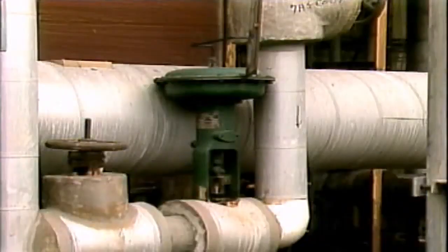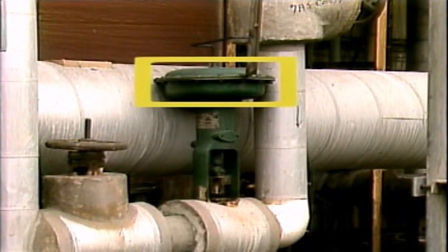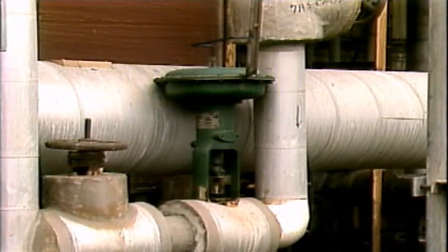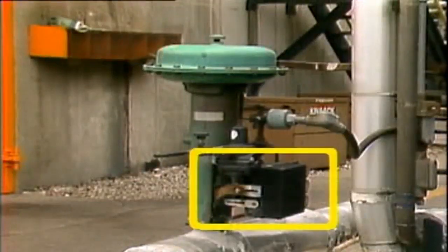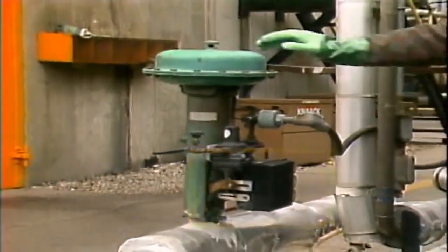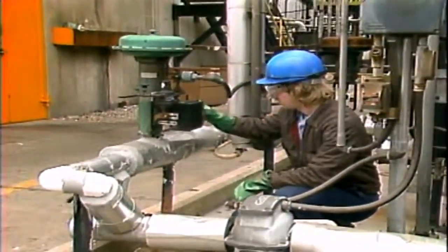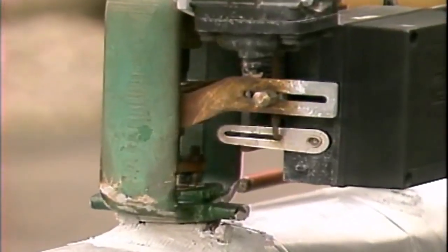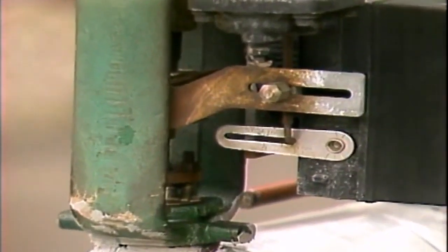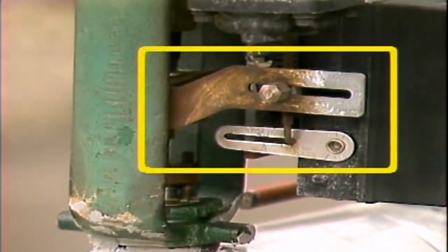Loss of air pressure could result from leaks in the actuator around the diaphragm edge, from leaks in the air lines to the actuator, or from a crimp that blocks the flow of air in an air line going to the actuator. If a positioner is used on an actuator, its gauges should be checked to make sure they have the appropriate air pressure readings. Sometimes problems with a positioner can also result from a loose or broken feedback linkage, so it should be checked